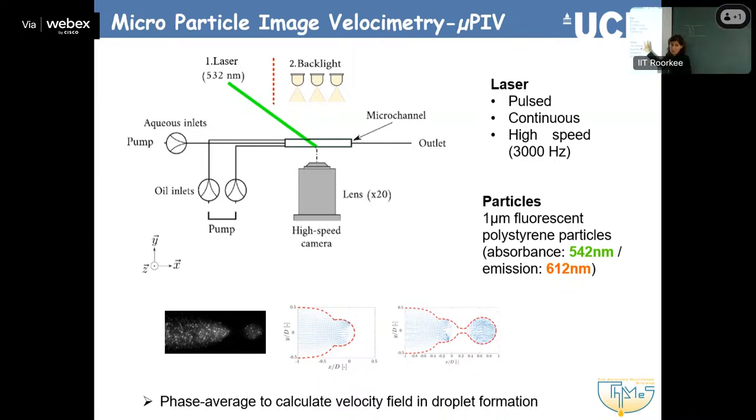Again, it is a technique that has been developed a lot, and there are various variations. I'll mention a few here. There are a lot of references as well. As I said, the standard one is easier to pick up. Then there are various evolutions. The micro PIV differs from the standard PIV in terms of illumination, as I mentioned to you. In the standard PIV, we have a plain laser sheet in large scale systems. In micro PIV, we have this volume illumination.